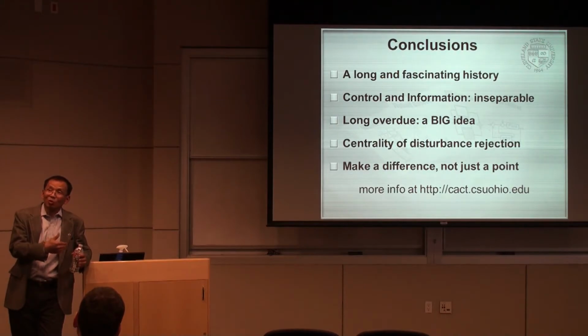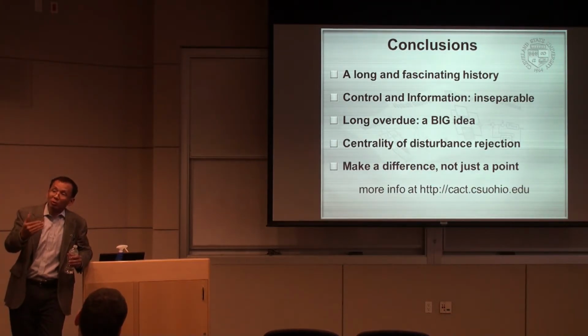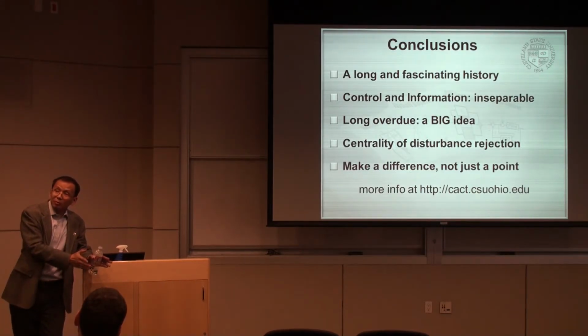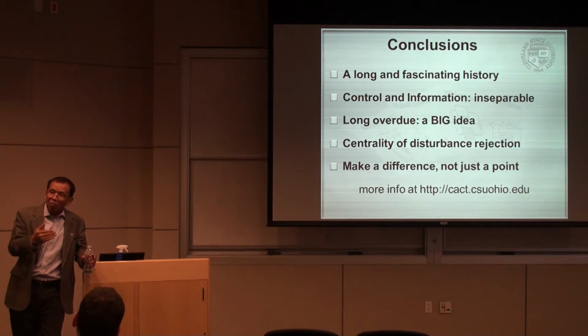I don't have time to go over the details, but information like that can be incorporated into the observer so that the observer doesn't require such a high bandwidth. If you assume you know nothing, then all of f has to be estimated by the observer. But if you know part of f, then the observer only needs to estimate the unknown part. Reducing the bandwidth is the holy grail in industry. You want to use as low a bandwidth as possible. This will solve your noise problem and your stability problem. But this is not emphasized in academia.